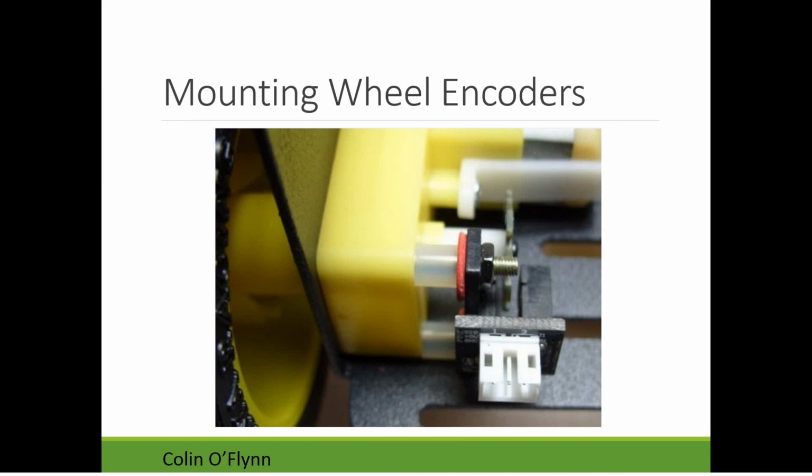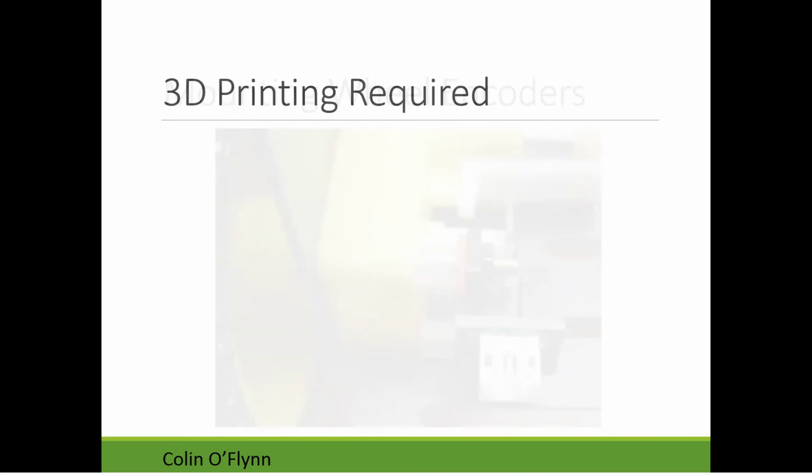As for the encoder disk itself, if you start to assemble the robot, you'll see a part that it can fit on. So here's the wheel. You have the motor here, and there's another shaft at the output. So basically the disk goes right here. The disk just turns with your wheel, so you can tell how far your wheel has turned.